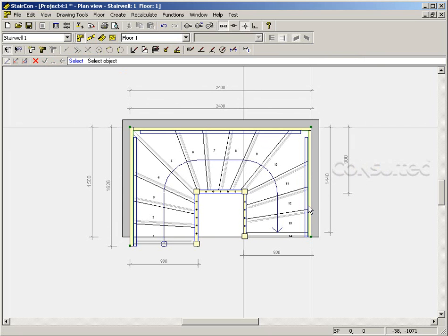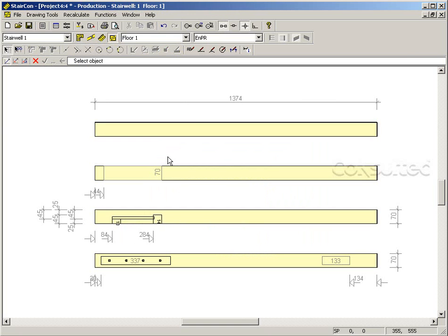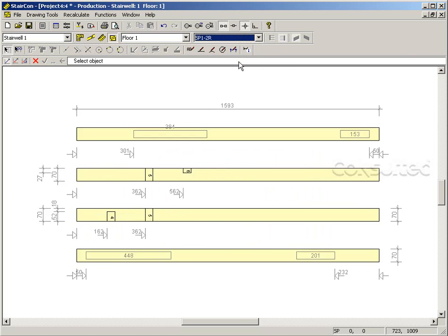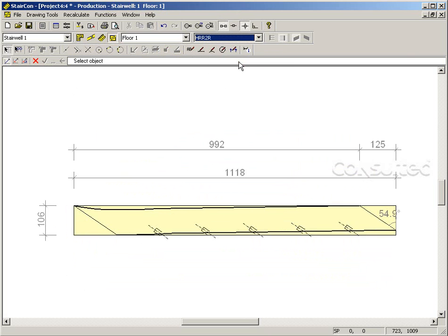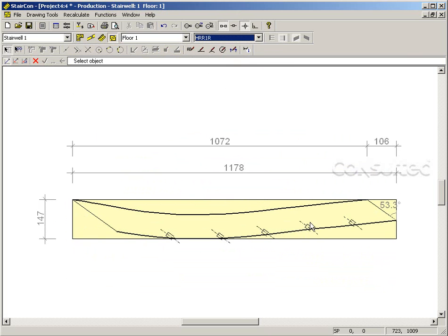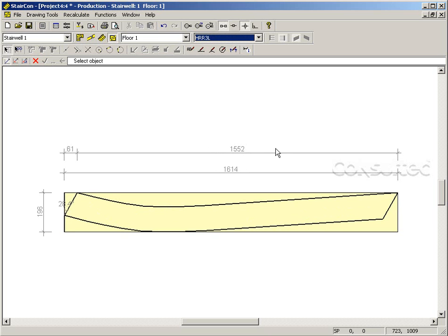I haven't shown now the CNC generation, but it's basically opening up, distributing them over the table with the predefined layouts, and then generating CNC code for all the layouts, and then we're done. So the most work is done here in the production view, also for the CNC producer: moving points, editing drillings, etc.